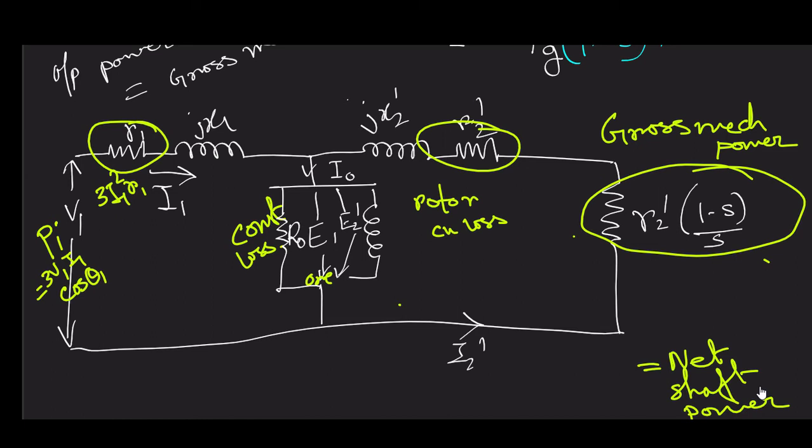then we can see that for slip, these two losses, rotor core loss and these mechanical losses, they are providing a kind of vernier action, means they are taking a responsibility of maintaining a constant loss. Stator core loss you cannot vary because it is dependent on your input side voltage and frequency. So what you will have here, that is pretty interesting, your losses will remain constant.